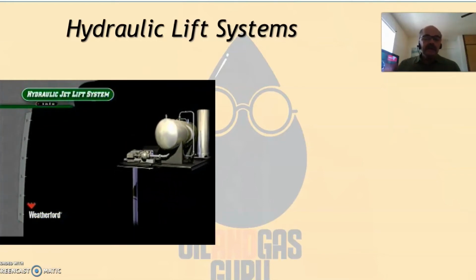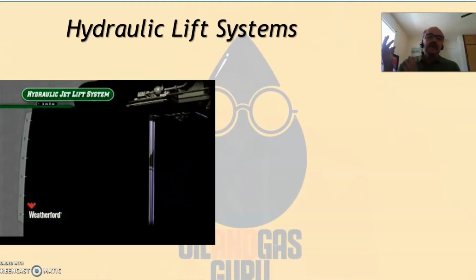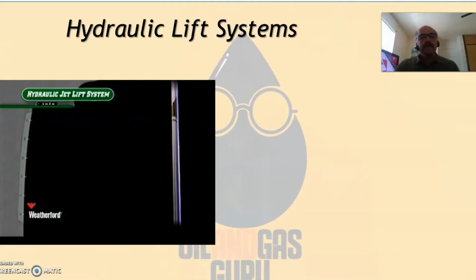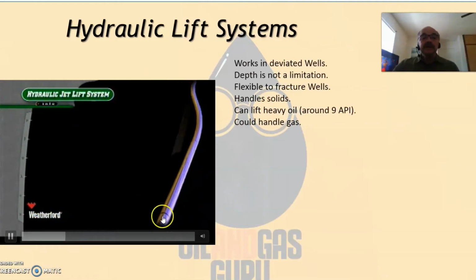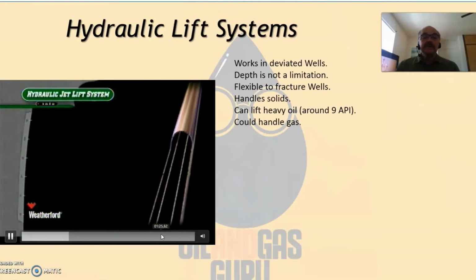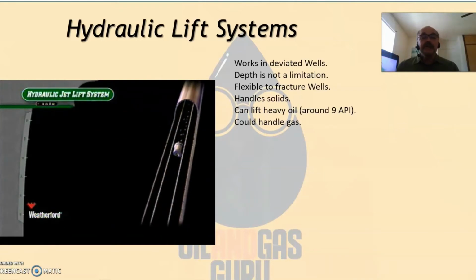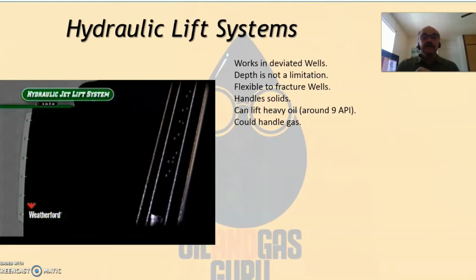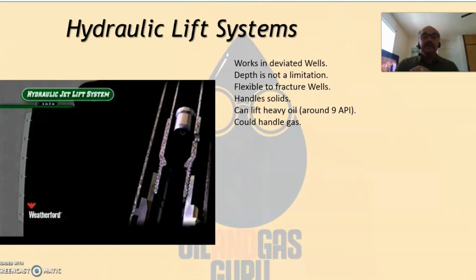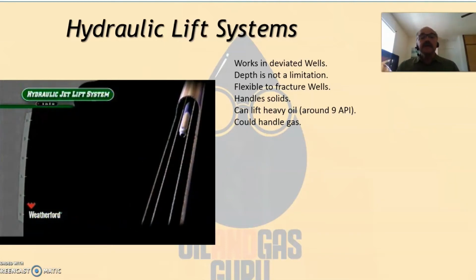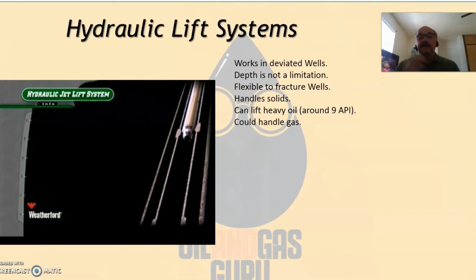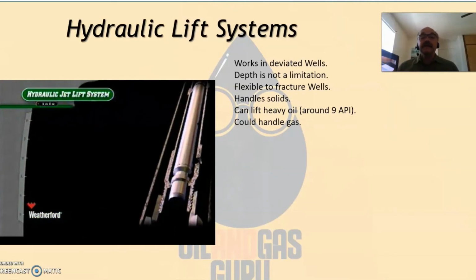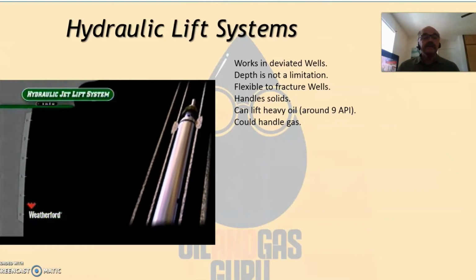It circulates, it separates, the oil goes to the tank, and the power fluid goes back in the well, and it creates a suction according to the geometry of the areas. That's why we drop those little bitty nozzles and things. And the pump itself has areas in there that create the pressure, the suction.